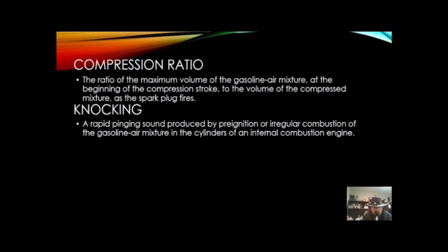It can even come on hot days while you're just going at highway speeds. Essentially, this is a bad thing. In normal combustion, the fire starts from the spark plug and radiates outward, like a ripple in a pool. When this happens, you get the most energy applied to pushing the piston out.